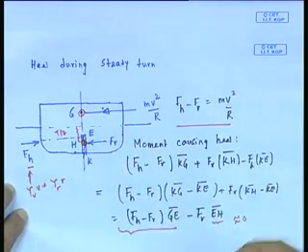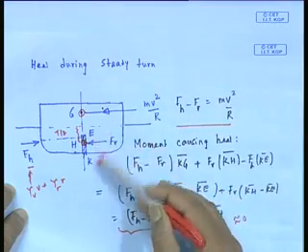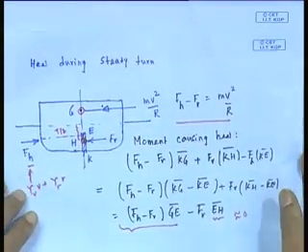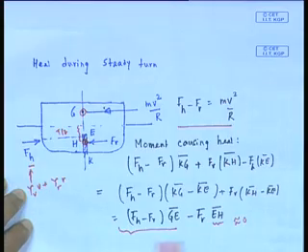Number of hull forces will be coming. Here, of course, we just made an approximation. In fact, in submarines things are much more complicated, because as it turns, it also goes down or goes up; it does not stay in the same plane. I just want to tell you on the side how the hull forces come. As it turns in the horizontal plane, it necessarily produces an upward or downward vertical force, pitch and all.